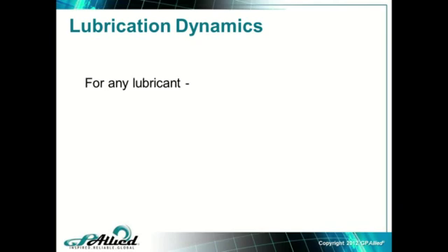So when we talk about lubrication, for any lubricant, as pressure goes up, what do you think happens to the lubricant? Now, this is generally where I'll ask, is lubricant compressible? And the answer to that is no, it's not compressible. If it were compressible, hydraulic brakes wouldn't work, hydraulic jacks wouldn't work, bearings and gears would not work the way they work today. So when we realize that lubricant's not compressible, then we've got to ask ourselves, well, what happens to the lubricant physically when we put more pressure on it?